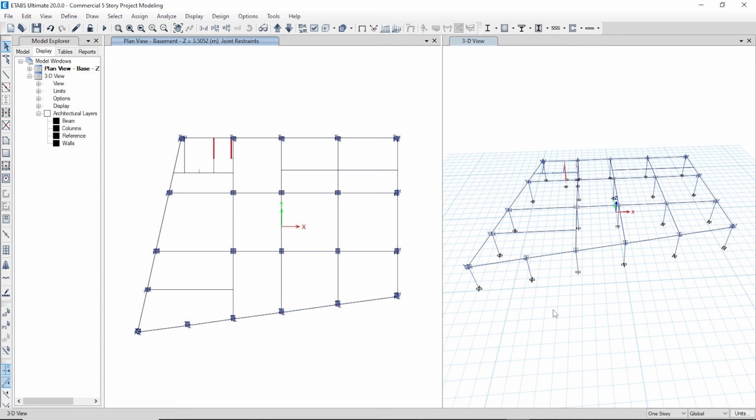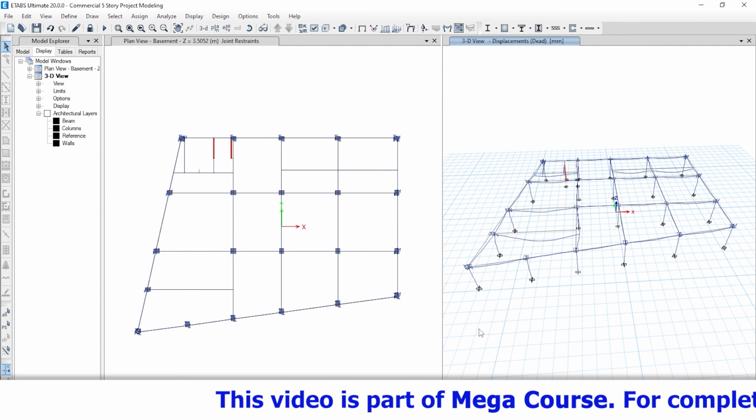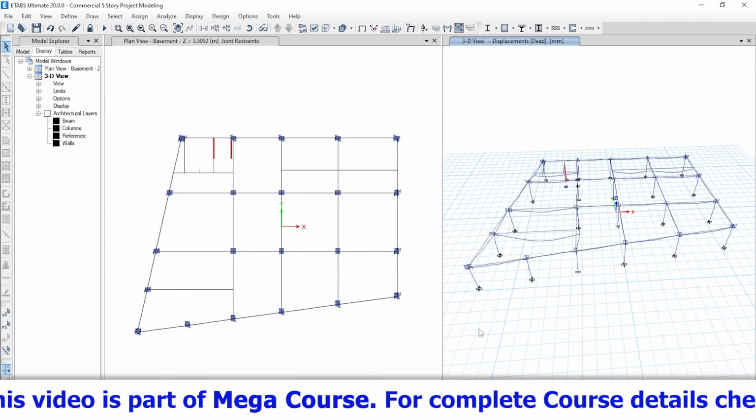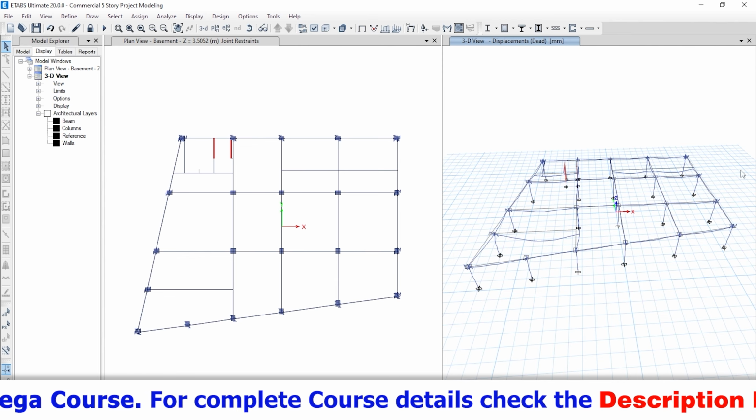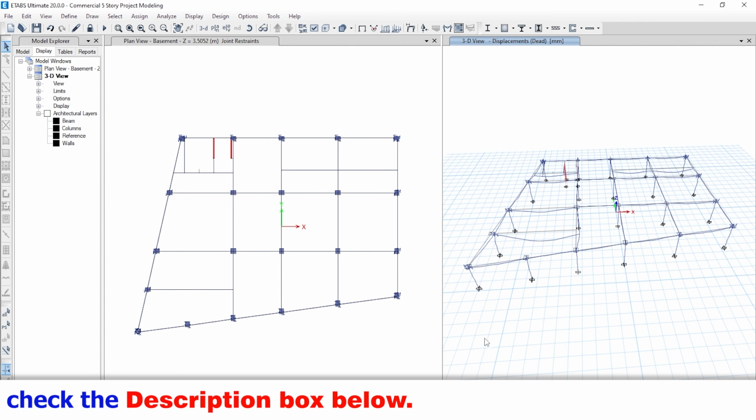Quickly click on the Analysis button to run the analysis. Here you can see this time none of the beams are failing and we got a deflection of only 0.7 mm. If you do not want that later on, when you reach the top 5-story level, you encounter a structural instability message from ETABS, then do make a habit of checking the structural stability at each floor level before placing slabs on it. This will help you to avoid mistakes at an early stage. Break the analysis.